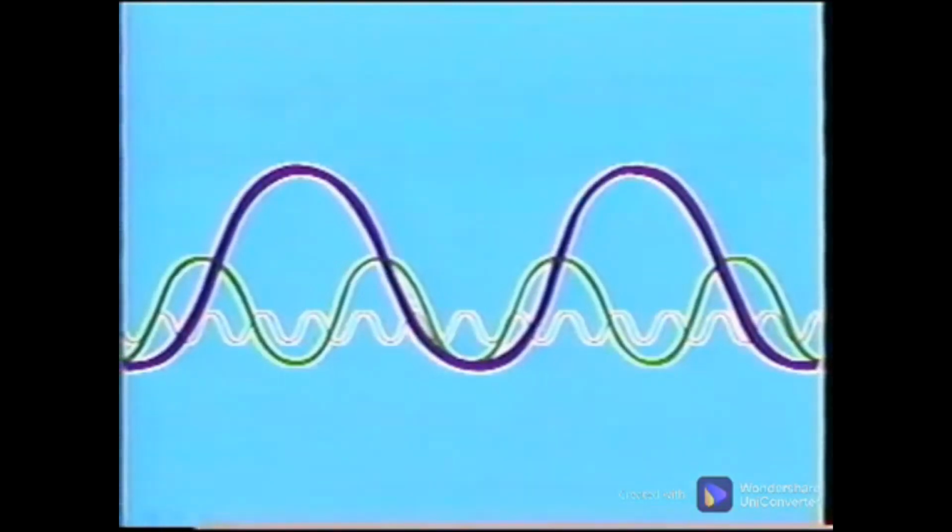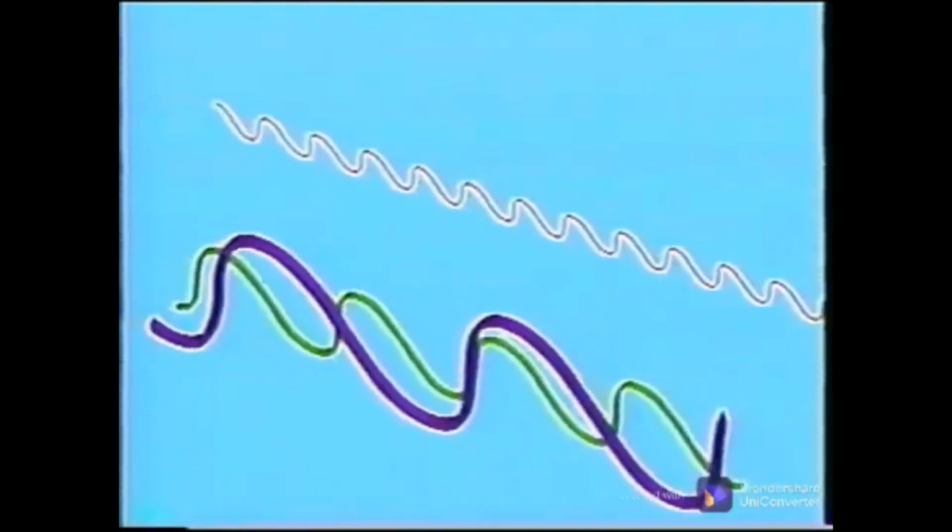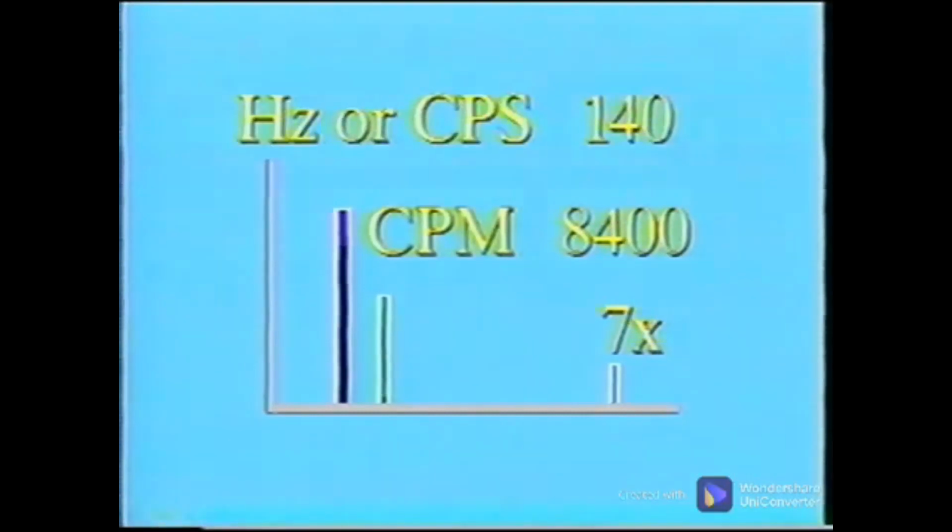Again, the processing separates the waveform into individual sine waves. The calculations are made which convert this data into a spectrum. This new peak represents energy that occurs 7 times during each shaft rotation, 8,400 times per minute, or 140 times per second. It is common for machinery to generate many frequencies that create a very complex waveform, and thus many peaks in the spectrum. Determining the source of the peaks and the severity of the problem is the challenge for the analyst.